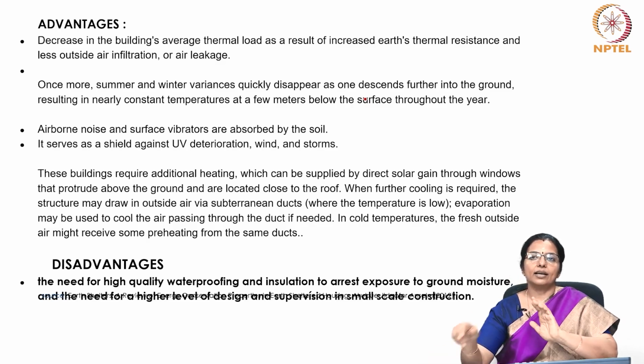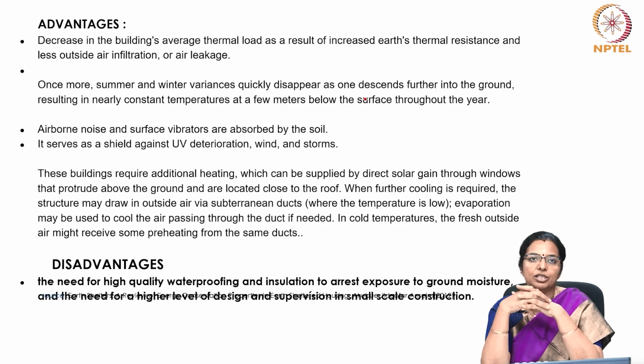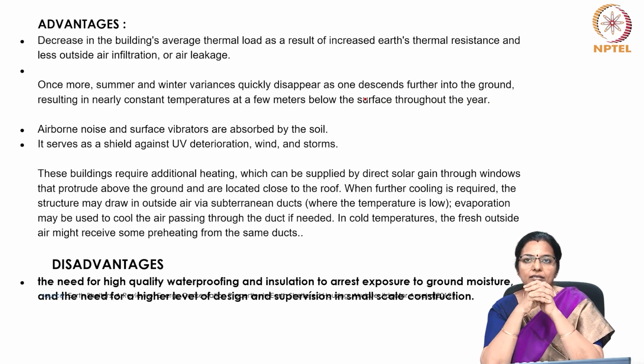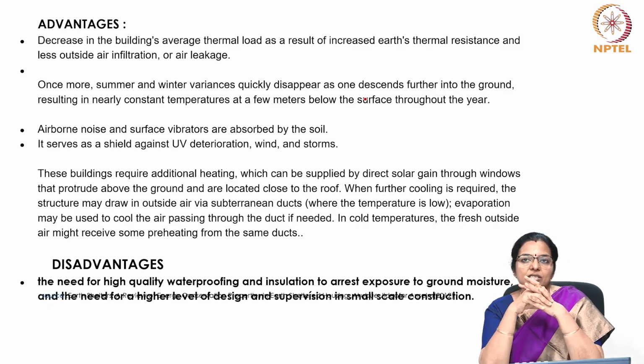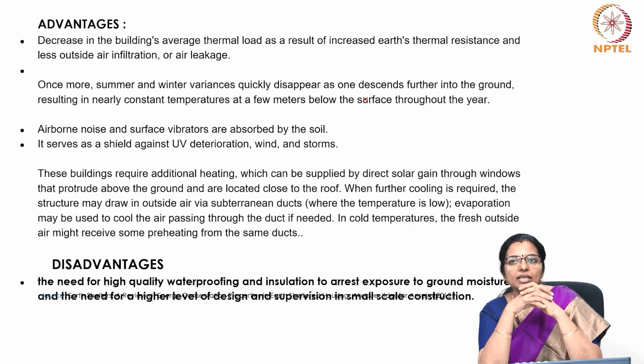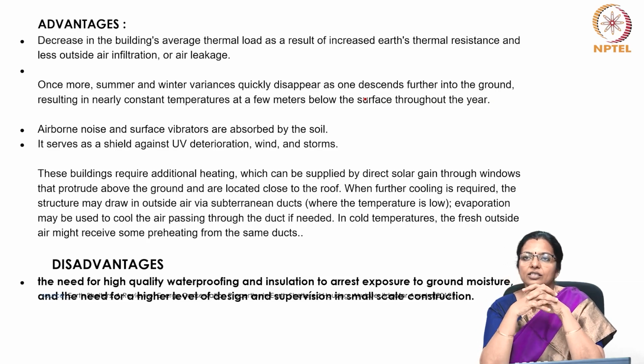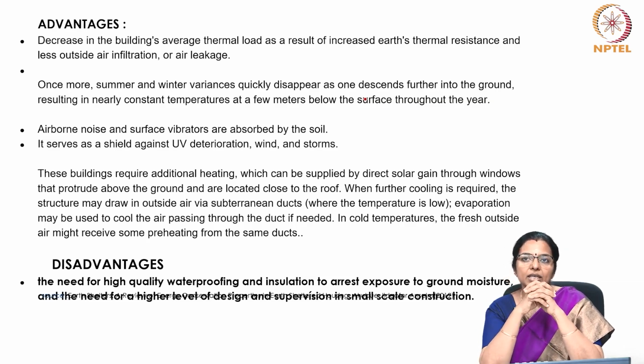Let us look at the advantages and limitations of earth sheltered houses. The advantage is that there is a decrease in the building's average thermal load as a result of increased earth's thermal resistance and less outside air infiltration or air leakage.